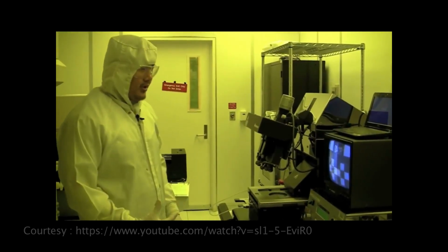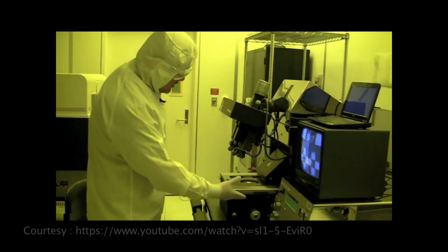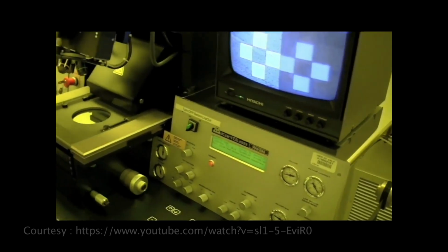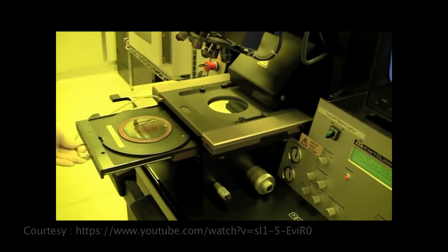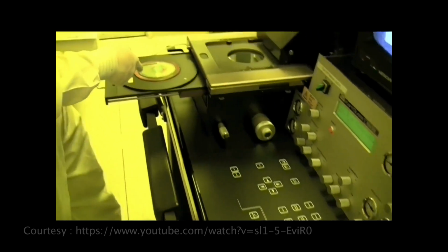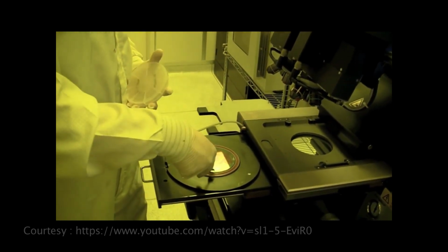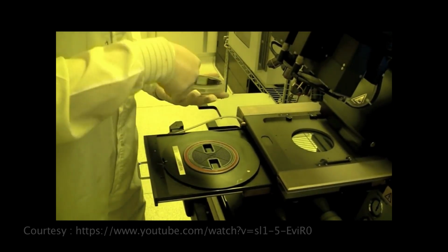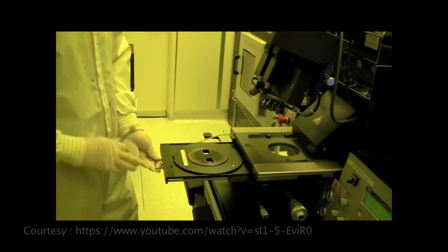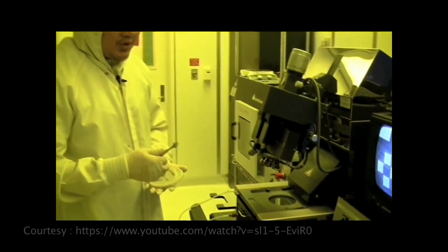So after exposure, you need to unload your wafer. So what you do is you would come to the screen, and it will say pull slide or unload exposed substrate. So you just pull it out, and then you press the enter button, and then the vacuum will be released. And you can take your wafer out. And then you put it back in. So that's how you unload your wafer after exposure.